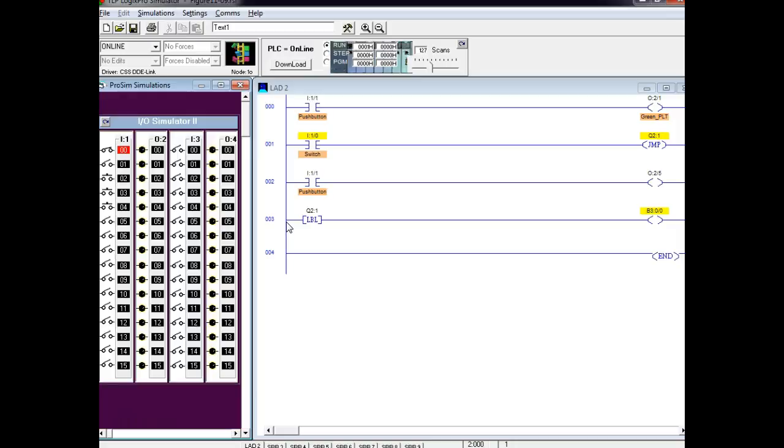You understand? PLCs scan inputs and they update outputs depending on the input. So that's what it goes. It scans the inputs, then it makes a decision on what it needs to do with those inputs, and then it updates that. So in other words, it jumps the last state. So if the output was on, it's going to stay on if you jump over it. It's going to stay on no matter what's going on.